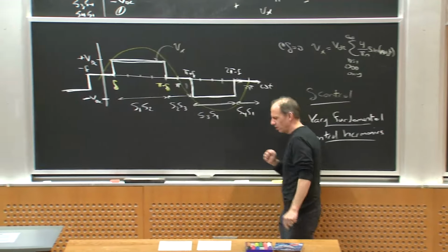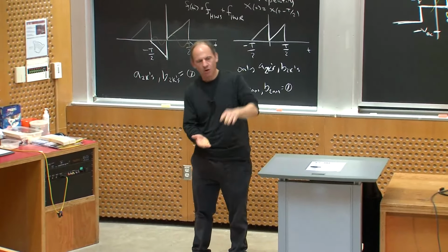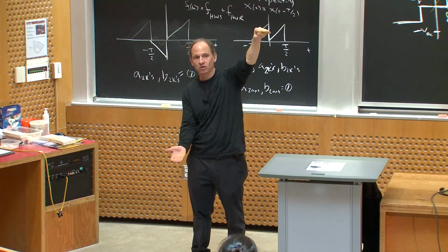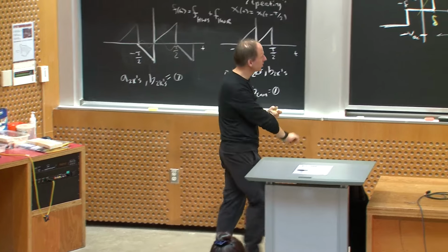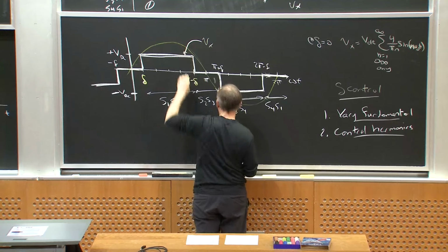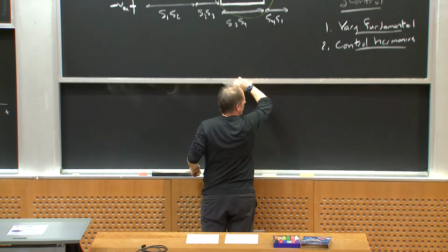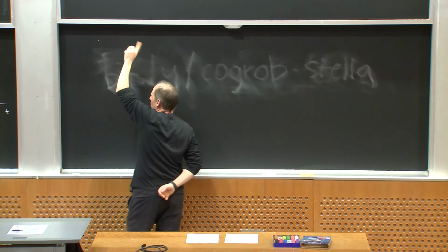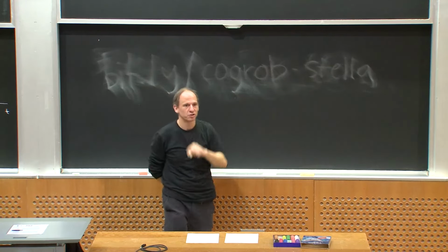What would I do in terms of varying the fundamental? Very often, if I'm driving a motor or something, how hard I'm driving the motor has to do with the amplitude of the waveform I'm driving it with. So if I can have some means of amplitude control, that's a good thing. Let's think about what the fundamental of Vx looks like. We can express Vx as the sum of odd harmonic sine terms only.